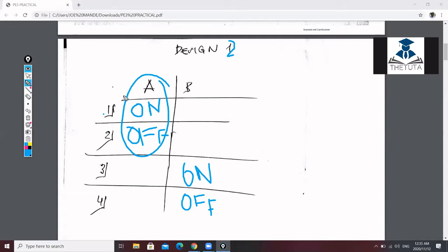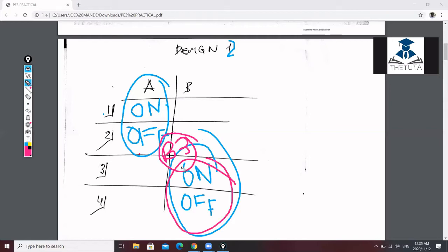This one must go off so that cylinder B will go in operation. So they are independent. In order for us to make a lock, we need to put a storage here. The purpose of this storage is to make sure that if one of the cylinders is in operation, the other one should not be. And once B starts operating, there is no need for A to go in operation. That's the purpose of that storage.